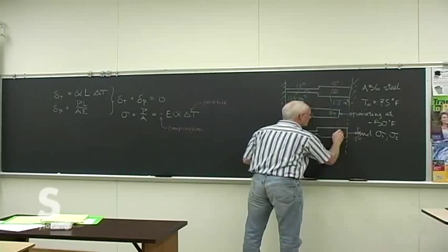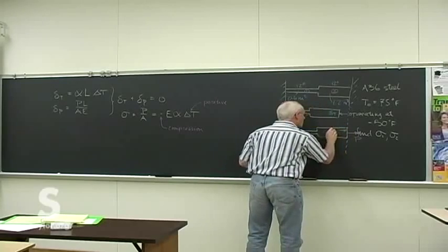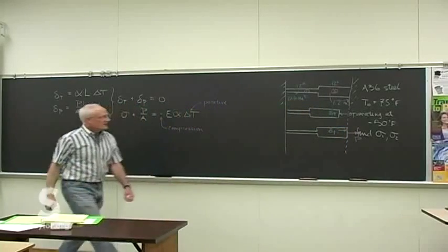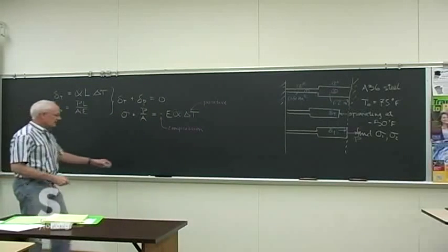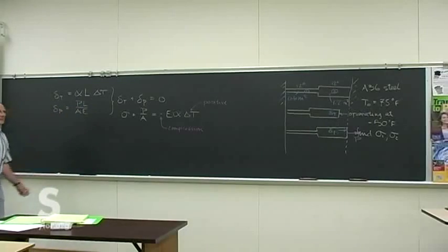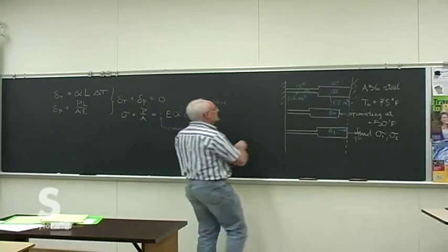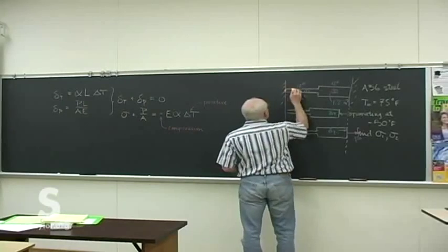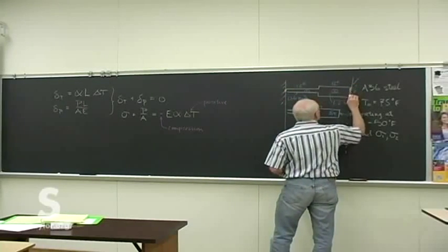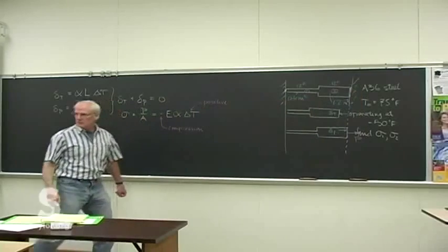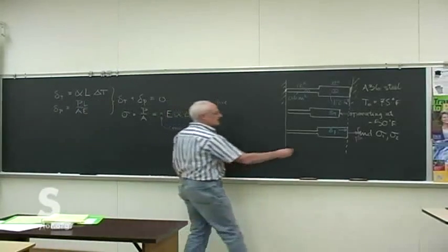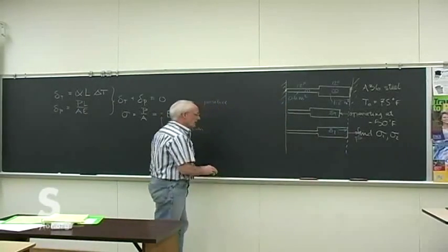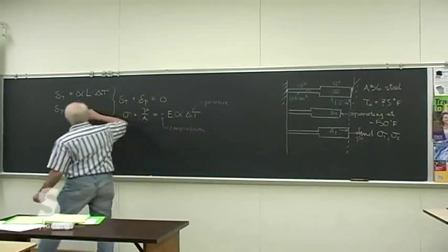By modeling that a change in length due to the tension we're going to have to apply to it. This, of course, means that in some way it's actually attached, maybe welded to those immovable supports. So as it lowers temperature, it tries to shrink but can't, and that gives us the reaction of the support pulling it back to its original length.